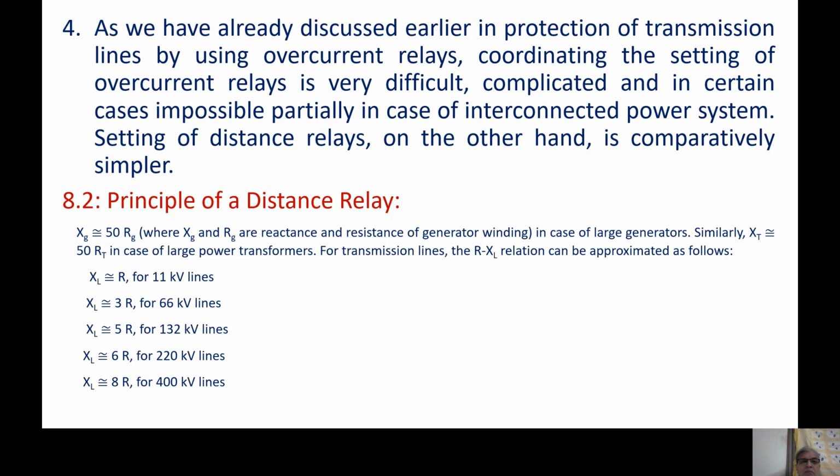Another problem is that in an interconnected system, for a particular fault, that means a fault at a particular bus, neither the primary relay operates nor the secondary relay operates, and some third relay which is not connected at all, and might be far away, will operate. This is known as sympathy trip. And sympathy trip does occur, because even today people are doing research on optimization of relay settings.